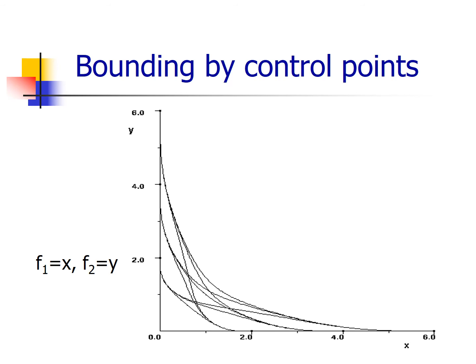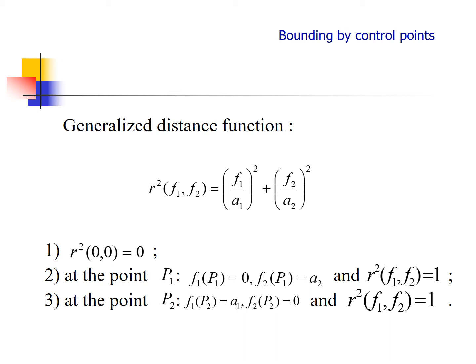We discuss here the first and possibly the simplest method of blend localization, bounded blending using control points. The idea is to place one control point on the surface of each initial solid and to require that the blend exists only between these control points. The control points are supposed to be relatively close to the edge resulting from the pure set theoretic operations, and it should be intuitively obvious what area is designated for blending. To satisfy such requirements, the displacement function should become zero at the control points, with the maximal value on or near the edge. Here you can see the following properties of this function.